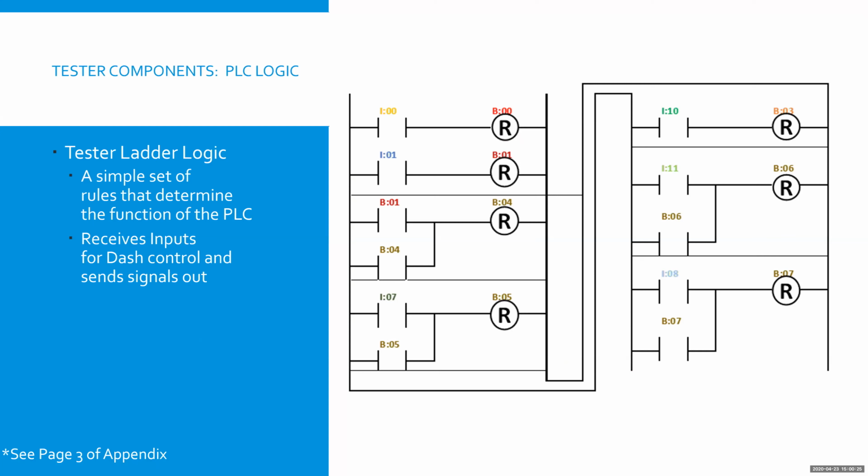Just to kind of go through the motions of what would be going on during this test, you would initially turn the key to the run position, which energizes the dash control, which is followed by the stabilizer light, the temp light and oil light turning on, in addition to 2 other lights on the indicator panel on the tester. So that signifies that all of those are working.